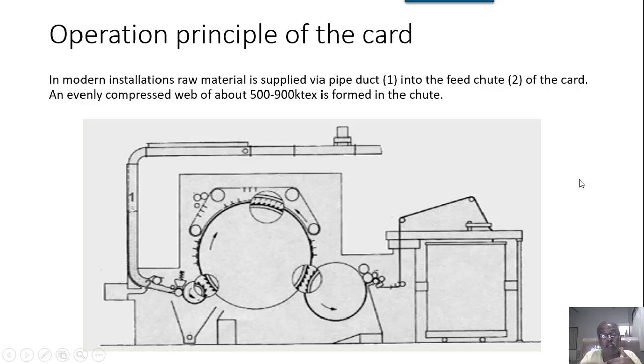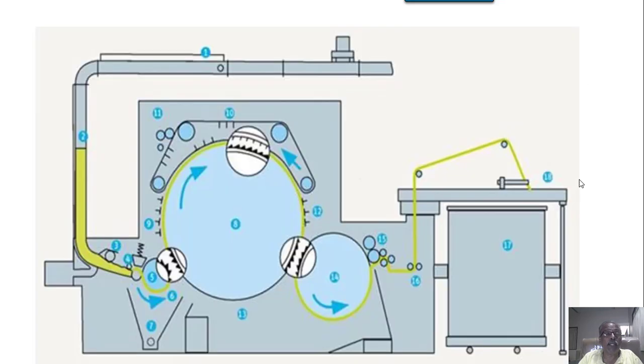When the reduction of mass is executed on a regular material, it will give a very regular amount of feed to the cylinder of the carding machine, and which will reflect in the further sliver quality. So that is the importance of the feed zone.